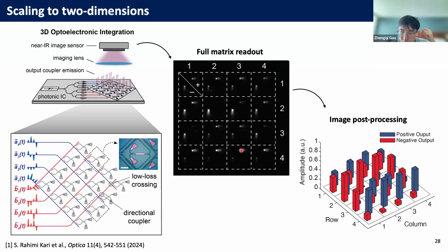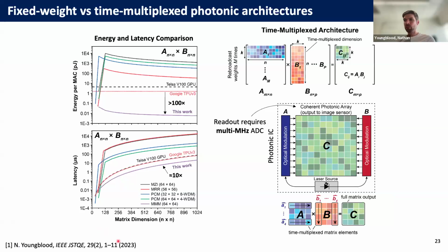Okay. I think the final question, how is the scalability of photonic crossbar array against the electronic GPUs, AI processors in terms of multiply accumulate operations per joule with increasing matrix size? Yes. So we have a theoretical paper on that. It's a bit of an unfair comparison, to be completely honest. I'm not an architecture guy, so I can't really simulate what does it cost to fetch from memory and do all of this. But if you take into account the input modulators, the optical power, the digital to analog converters, EO conversions, all of that, the photodetector current that you need to get relative noise, the best you can do is what's plotted here for these different architectures.